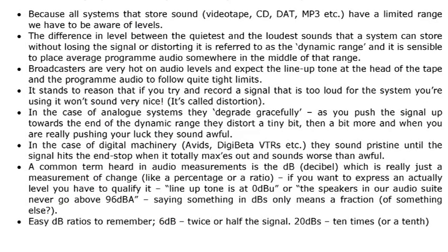A common measurement that you'll often hear in machine rooms and other audio places is the decibel, which is a relative measurement between different levels of sound. You'll quite often hear somebody say, oh, the line-up tone on the head of that tape is 6 dBs too low, which means that there's a discrepancy between what the line-up tone should be and what they've measured.